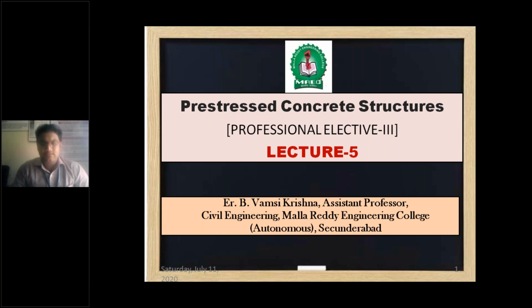In that way we discussed different types of pre-stressing systems. Along with that, what are the stages of pre-tensioning? They start from anchoring the rods, pouring the concrete, and after it sets, doing the stressing. So what are the stages of pre-tensioning and what are the devices used in pre-tensioning, we discussed in the previous class.